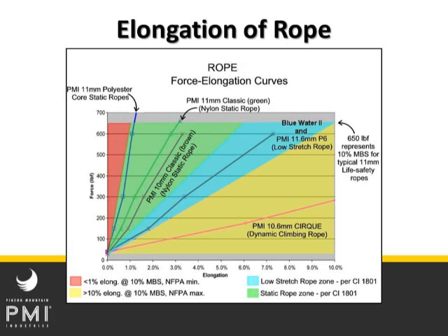You should not go to skinny ropes just because it passes the UIAA test. You should probably be sticking with the fattest, closest thing you can get. Some people still make 11 millimeter ropes. I sure wouldn't go less than 10.6 with big guys, because you lose the impact ability, and the forces go up very quickly when you take a fall as soon as you do that.